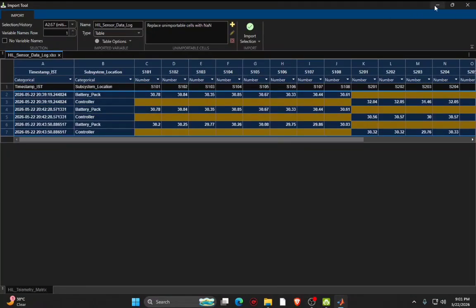From this Excel sheet, if I run this for 30 minutes, I will have much more data on which I can train a model, like a Gaussian model or a tree model, with which I can make a system, or you can say a thermal system, which will predict if the temperature goes above a certain degree in sensor ID 010 and 015. That means there is a problem in the temperature sensor, which will cause a battery malfunction or a controller malfunction in the future. So I am going to make that thermal subsystem, or you can say thermal control system, in the future. But for now, I have demonstrated the hardware in the loop concept with practical performance on the RP2040.